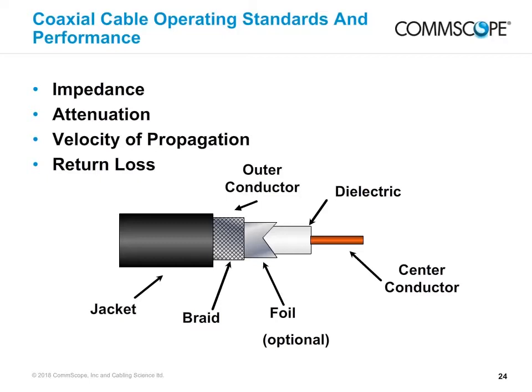Return loss is the ratio of the power of the outgoing signal to the power of the reflected signal expressed in dB. Structural return loss is the measure of power loss in a cable caused by discontinuities in the cable conductor or dielectric. If these discontinuities are regularly spaced along a cable, they can cause severe transmission losses for frequencies whose wavelengths are fractional proportions of the distance between these discontinuities. Lower numbers are better in both cases.